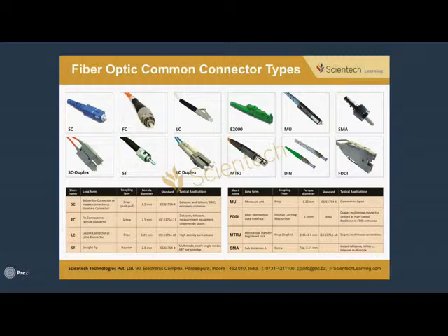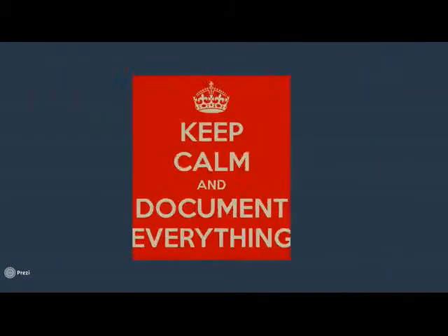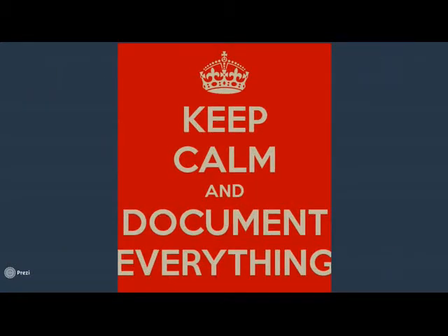The MTRJ connector is unique in design because it incorporates two fiber optic cores into one assembly without the use of a clip. It is always considered a duplex connector. The MTRJ is also a small form factor connector. Now, there are a few even newer styles coming out, and I imagine there will be new ones tomorrow. Remember to keep calm and document everything.